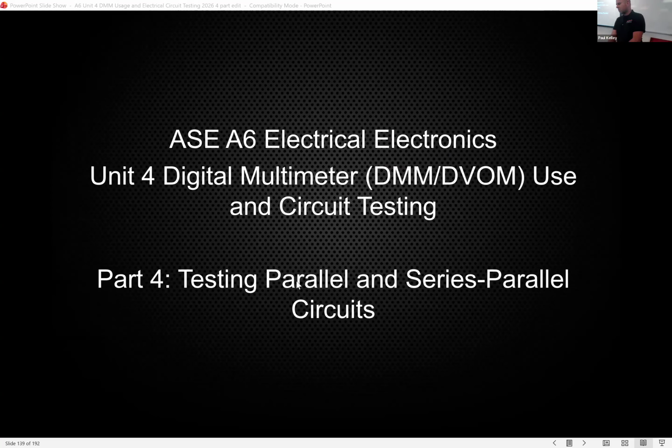And same with the series parallel. So we'll go over it because these circuits function differently. They have a different formula, for example, for calculating amps. They have some different theories as to, when we talk about series, if you want to add light bulbs, that's great. You add bulbs, that adds resistance. But on a parallel, if you add bulbs, you actually reduce resistance, which means you increase the amperage, which means you'll blow the fuse or cause damage and whatnot. So just make sure you understand the application of Ohm's law correctly, more so than how to do the Ohm's law, by the way.